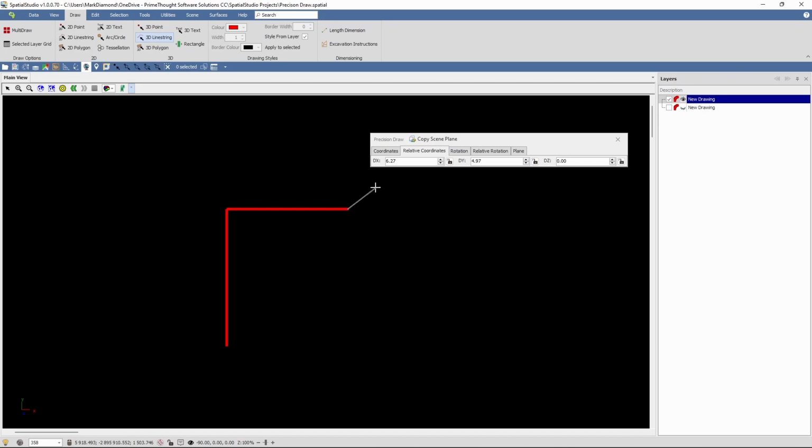So in this case, I wanted to use this point over here as the starting point to take the relative coordinate from. So I'm going to lock the Y coordinate as it is, and where my mouse is over there, so I can use the Y hotkey to do that. So it's the same hotkeys as for the Coordinates tab, X to lock X coordinate, Y to lock Y coordinate, and Z to lock Z coordinate. The only difference is these are relative coordinates here. So as before, I always make sure I first click on the dialog to make sure it's active, and then I come back in my scene and get to the exact position that I want where the Y coordinate is, and then I can hit the Y key to lock it. And as you can see, there we go, the lock is on and the relative Y coordinate has been locked. So I'll begin drawing now.